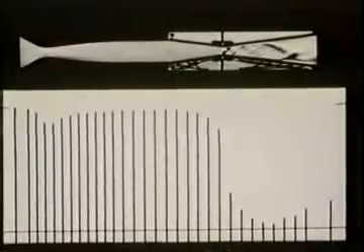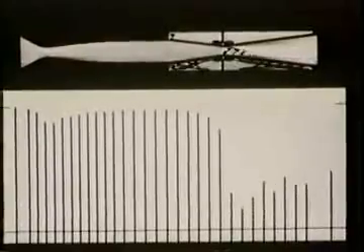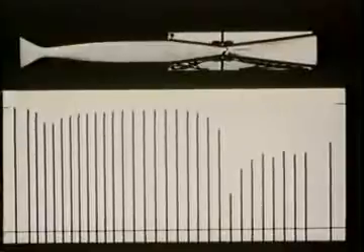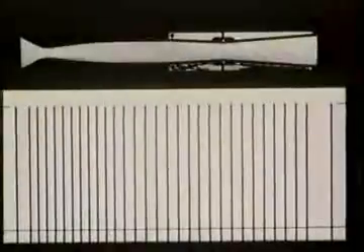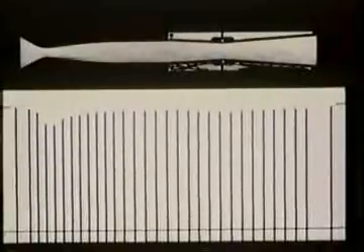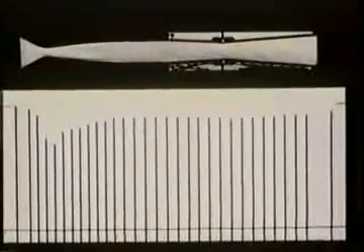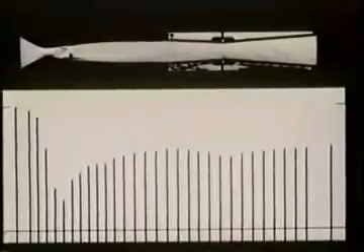Now let's make the second throat slightly larger than the first. As the valve is opened, the first throat chokes, and a shock wave appears in the nozzle. Then the second throat chokes, and we can no longer affect the first shock wave, only the second one.